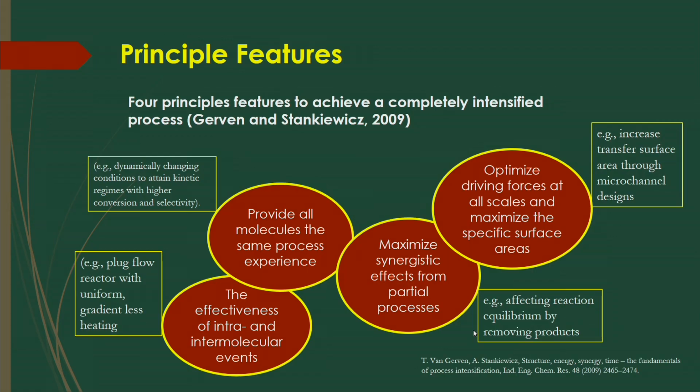This transfer coefficient depends on different operating variables of the process. If you are doing absorption of carbon dioxide gas, or gas phase absorption in a liquid medium, the overall mass transfer coefficient is considered as a proportionality constant.